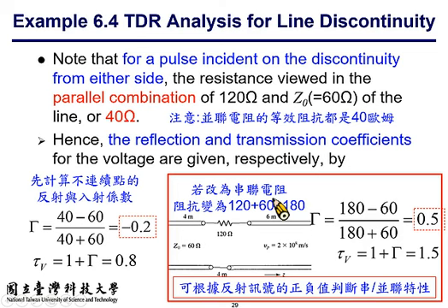All right. So to proceed with this problem, let's take a look at the equivalent impedance observed at this point. How many impedances can you observe at this point? You observe a series resistance of 120 ohm and the characteristic impedance of the transmission line, which is 60.